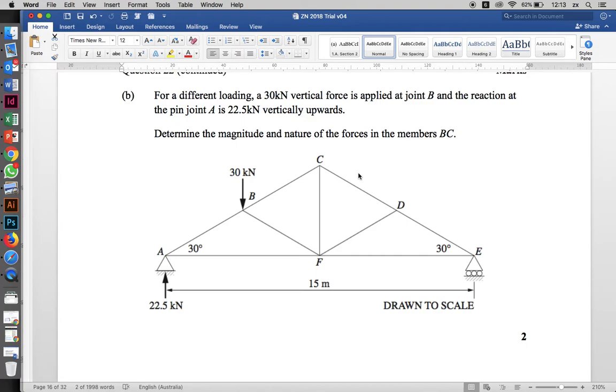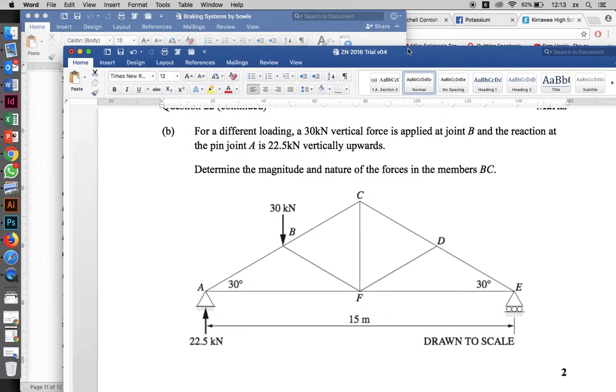Okay, so what I would do is I would cut through this section here. This will always be a lot clearer when I can draw on the board, but if I cut through this section, this BC to AF, I'm going to have 3 members exposed, BC, BF, and AF. They're the 3 that I'm going to be worried about. Now, just for the sake of this,